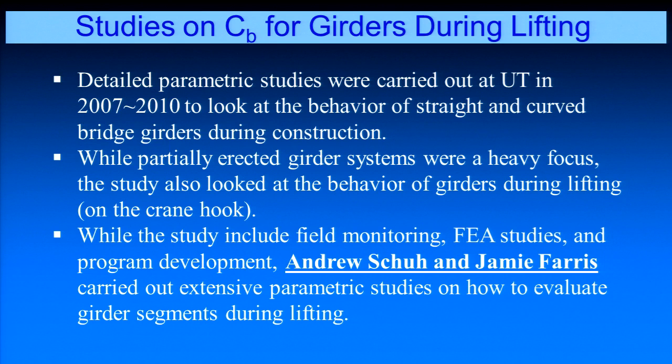Now, girders during lifting are always something that some engineers have faced, and you have to scratch your head, because during lifting, in order to evaluate the buckling capacity, you have to put in an unbraced length. So if you're going to say I have an unbraced length, you have to ask, well, what's bracing the beam? The crane's just picking it up in a sling.